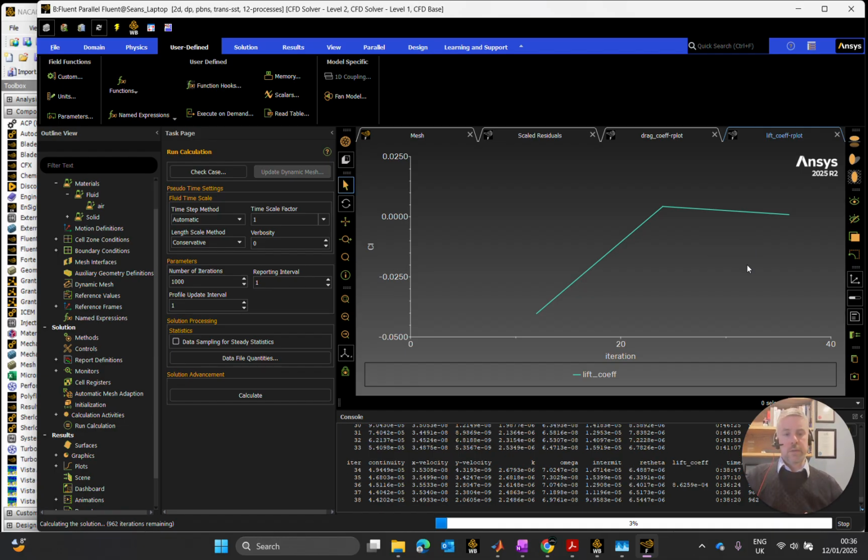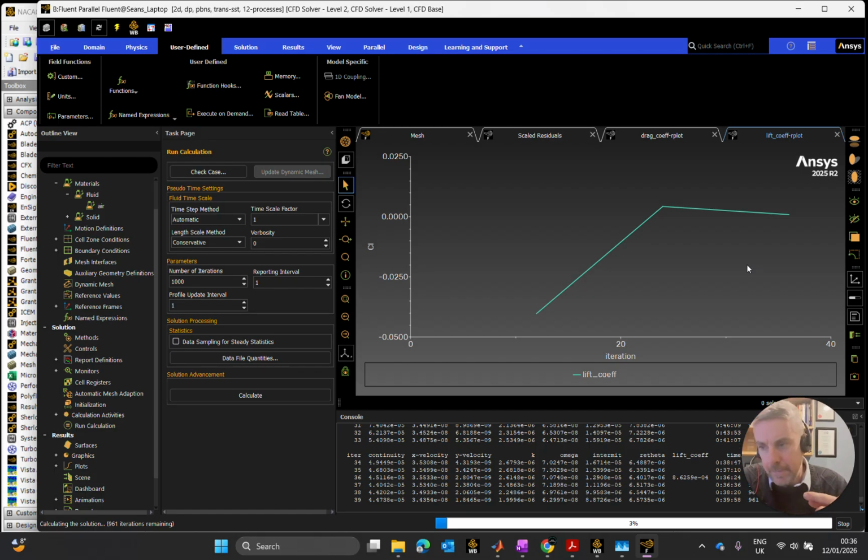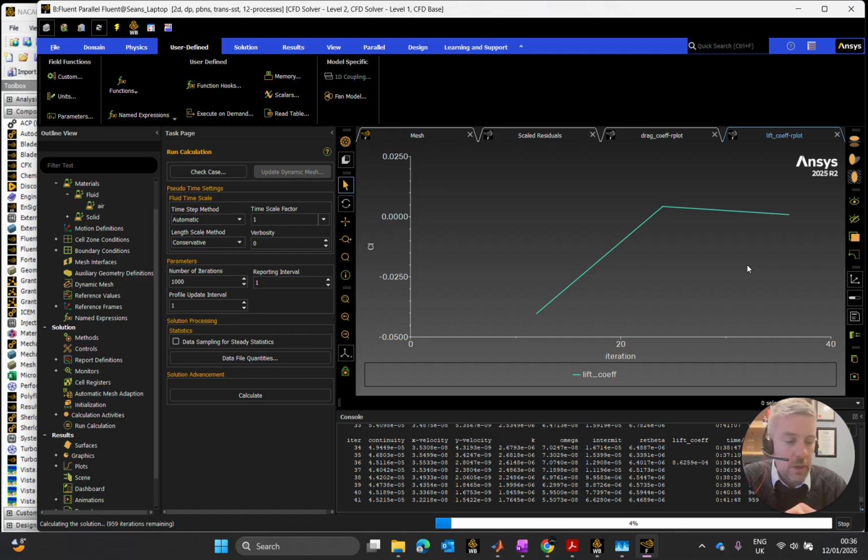I would expect 0 lift thereabouts, albeit it's remarkable, just as a pure aside, that the NACA 0012 aerofoil shows a negative lift characteristic at specifically a Reynolds number of 50,000 at a 0 degree angle of attack, and it has stall characteristics as well. It's an odd airfoil for that matter. There are an awful lot of papers done on the NACA 0012 for that reason.